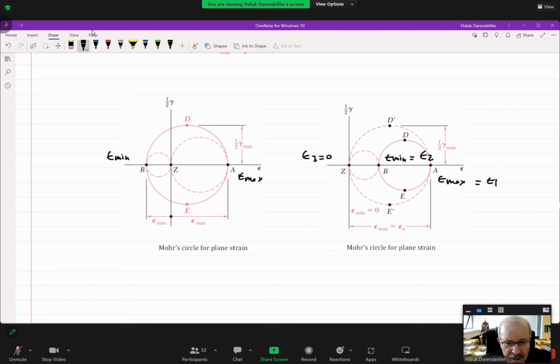On the other hand, here, this is the first principal strain. Since the second one is zero here, this is equal to the third principal strain. Now, look, the tau max here on the left is equal to 1/2 tau max in plane. Why? Because one principal stress is positive, the other principal stress, which we found, is negative.